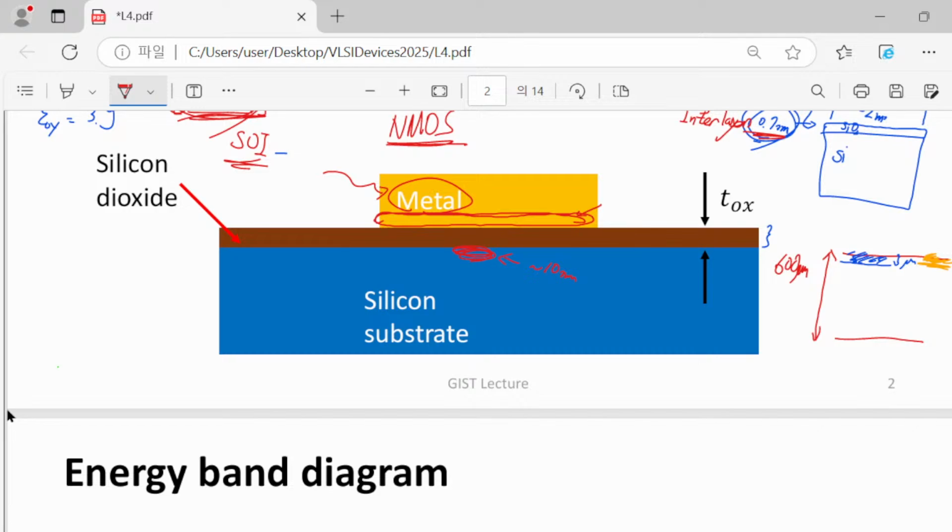So if we introduce, for example, a thicker layer or a shorter layer, then we can control the work function, and the desired work function range is given. For example, from 4.0 eV, this is closer to the N MOSFET application, and if we go to 5.0 eV, then this is more suitable for P MOSFET application. And by controlling the fabrication process, we can control the work function between these values.